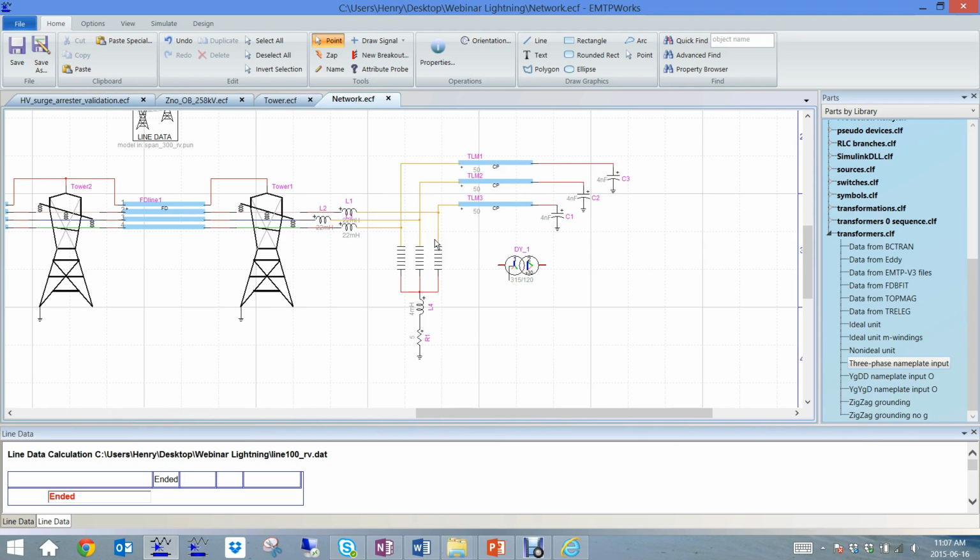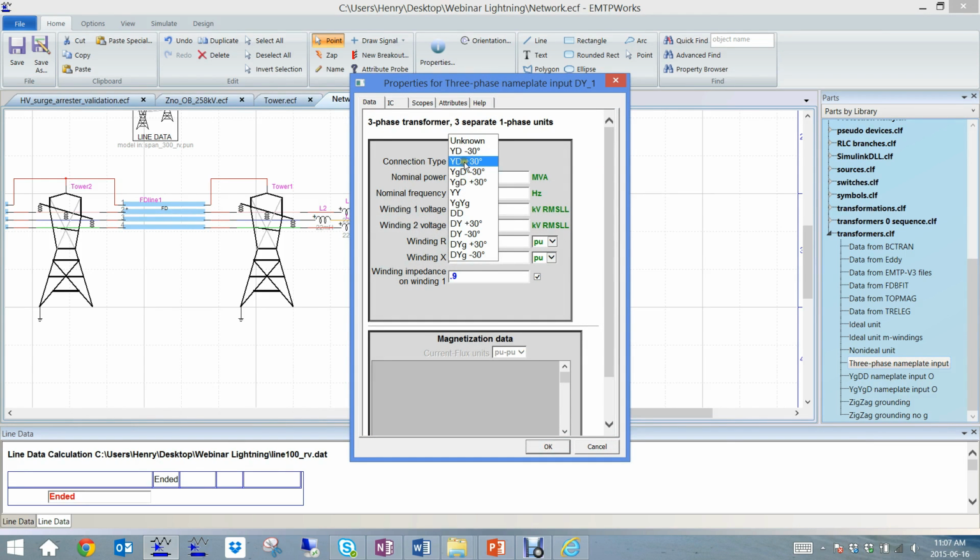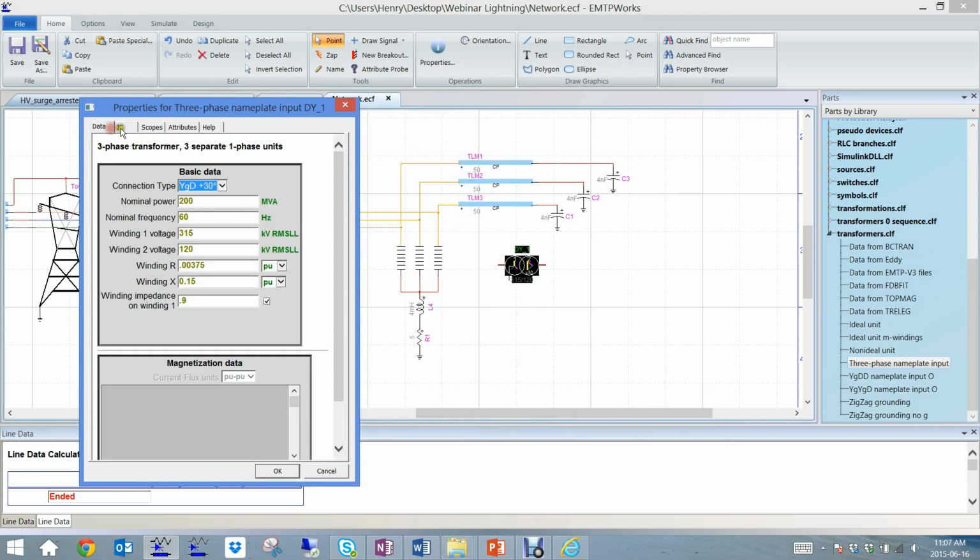But when you get to high frequency, if you remember from class, the inductances are like an open circuit. So in the end, the transformer is just an open circuit. And what becomes important now is the stray capacitance of it. I still model it here if we want to initialize the simulation at the power frequency, but it's really not important, so I don't pay a lot of attention to that. I put a kind of random value, it doesn't matter.